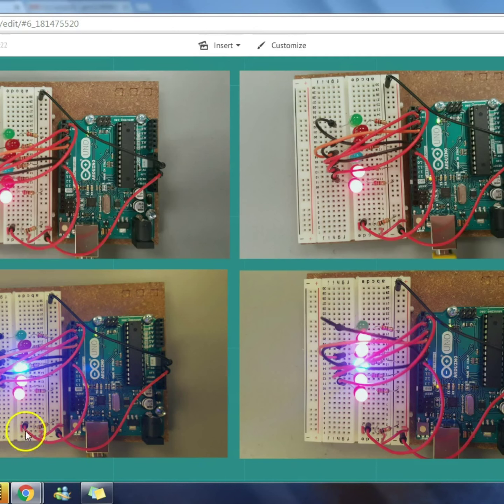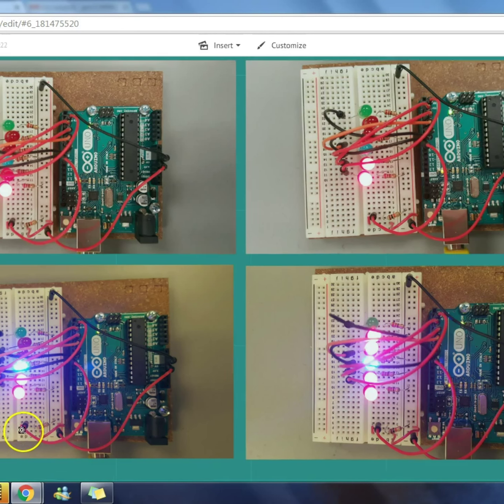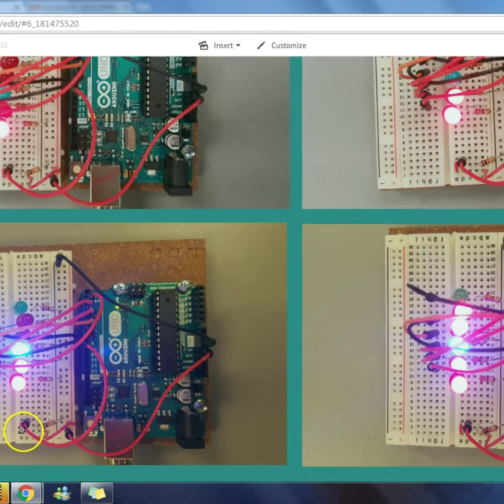As you can see, we did not incorporate our tilt switch. This is due to the prongs not reaching the contacts in the breadboard. Instead, we have a little jumper wire giving power straight to switch pin 8. And if we removed this jumper wire, it would have the same effect as if we tilted the tilt switch, which would cause an incomplete circuit.